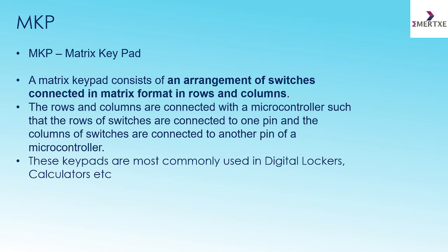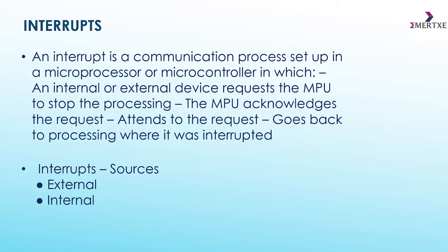Now moving towards the MKP. MKP stands for matrix keypad. A matrix keypad consists of an arrangement of switches connected in matrix format in rows and columns. The rows and columns are connected to a microcontroller such that the rows of switches are connected to one pin and the columns of switches are connected to another pin of the microcontroller. These keypads are most commonly used in digital lockers, calculators, etc.